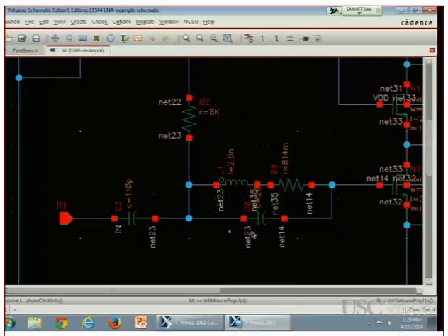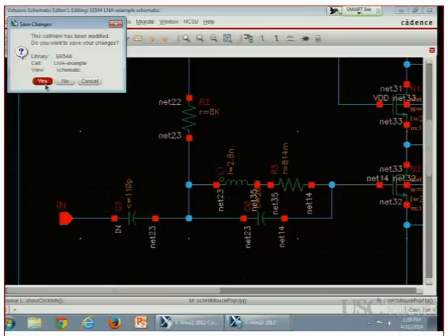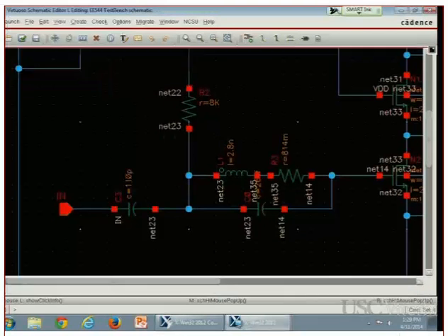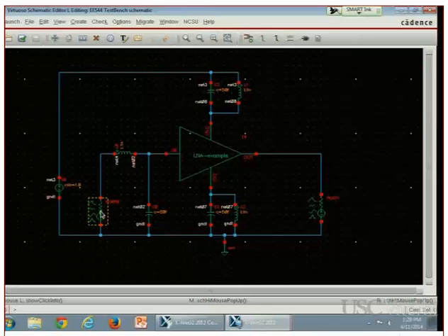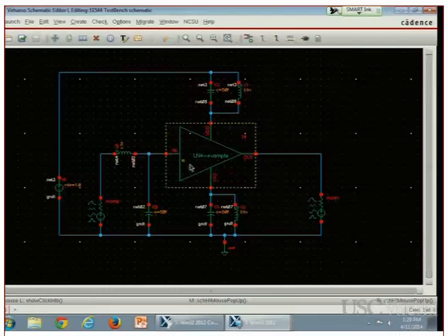Also, this right here combined with this, so this tank circuit and this capacitor basically alter the input impedance to match this over here. So this is a 50 ohm in series with a 1 nanohenry inductor, which is in parallel with a 50 femtofarad capacitor. So all the matching has to be internal in your circuit. When you get to that second part, you'll have to include the matching inside your circuit.